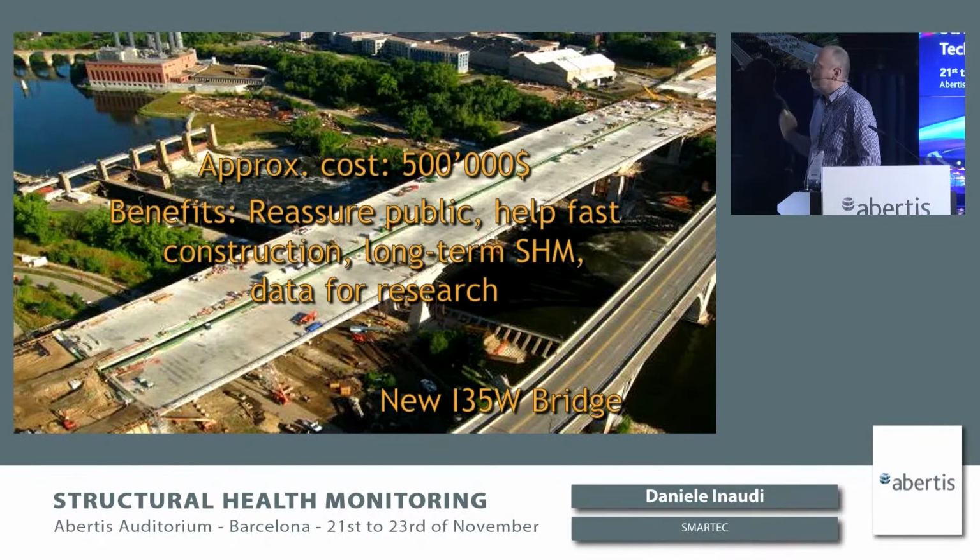At the same time, the monitoring was also helping the fast construction schedule. The bridge was built in 1 year, from collapse to reopening of the bridge. So it was a quite interesting project from the point of view of scheduling, installing a monitoring system, etc. And we were using some of the sensors to help the fast construction pace, for example, analyzing how quickly the concrete was hardening so that they could cast the next phase, etc.